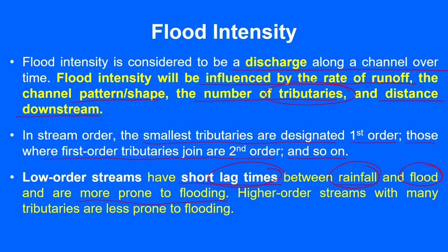If you are having many first order streams, then that area is not at all good, as it will have a shorter lag time. Higher order streams with many tributaries are less prone to flooding, because they have a higher lag time. You can keep this in mind.